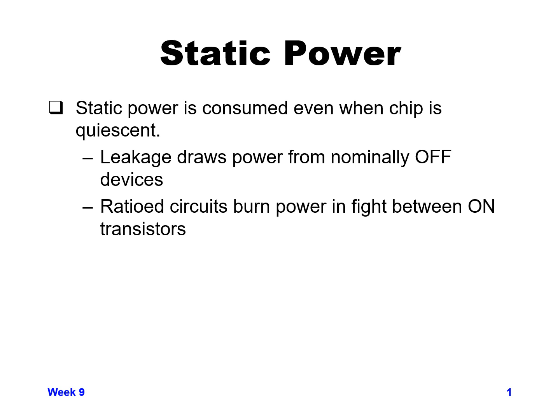So that leakage is going to consume some power. The same would be true if you had an inverter that's pulled down to 0. The NMOS device would be on, but the PMOS device would be off, and the PMOS is leaking in that case. So in either case, whether you're pulling to a 1 or a 0, there's going to be some leakage going through the device that should be turned off.